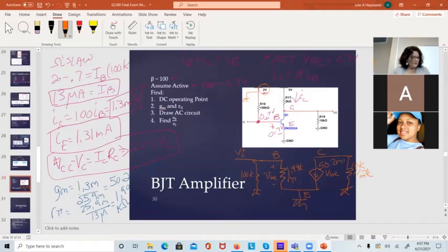So we could go through and calculate the gain for that. We're lucky here. My input voltage is tied directly to the base. The emitter's tied directly to ground. So in this case, VN equals VBE. And I have this current source going to ground. That's also going to ground. So these are connected together. My Vout is here. So the current source is 50.2 milli times VBE.